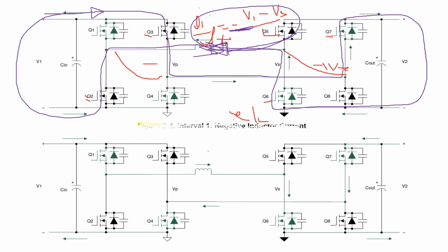If you still do not understand what I mean by interval 1, interval 2, interval 3, and interval 4, based on what we have covered, this is what it simply means. Interval simply means the change in the inductor current when the primary side and secondary side voltages are controlled by the switch waveform.